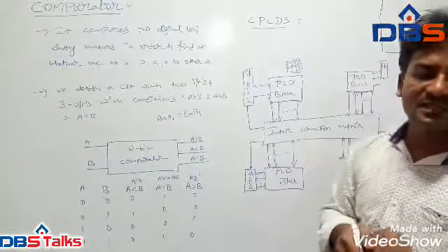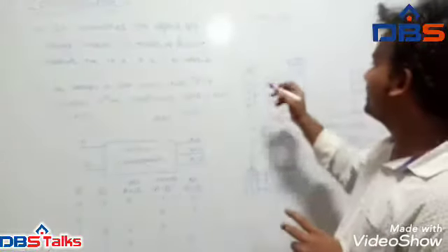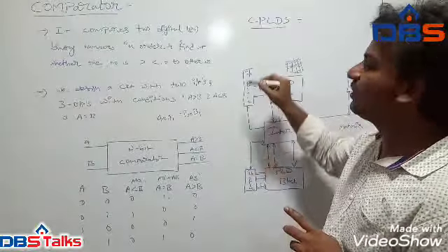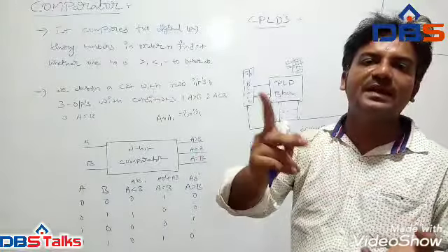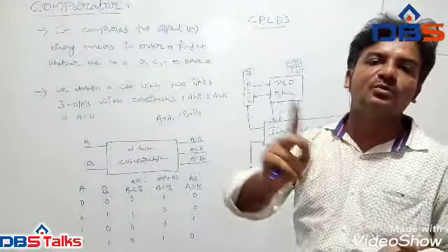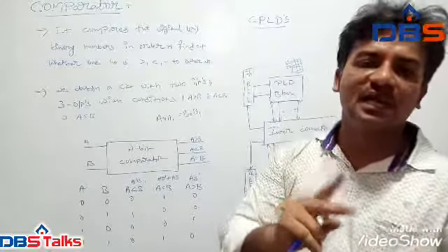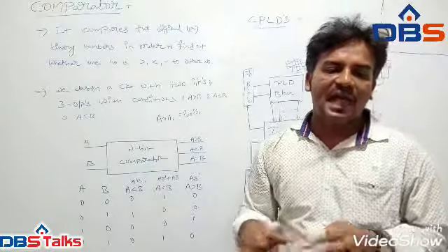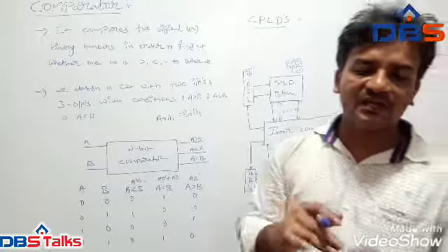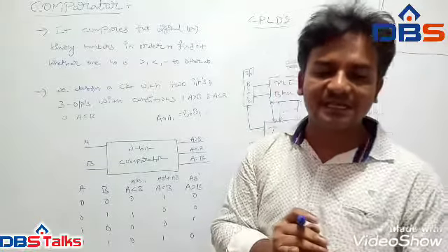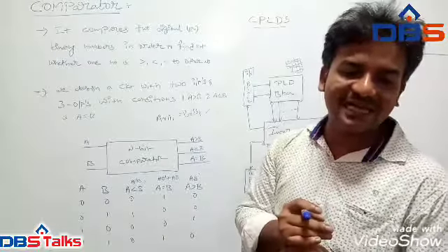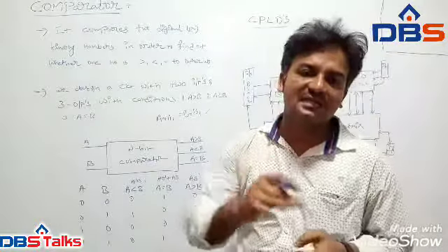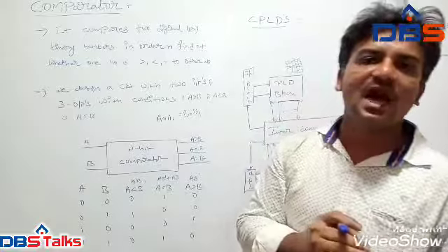So it will be manufactured with a tri-state buffer to suitably enable the pin as input or output. We use the tri-state buffer acting as a switch. It turns on if the pin is to be used as an input pin, or the tri-state buffer is disabled when the pin acts as an output pin.